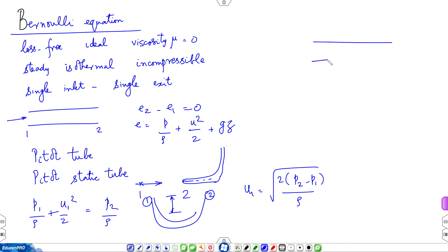Let us say this is a duct, then the pressure is the component of stress that acts normal to the surface. So, you create a small tap and let that pressure act on another surface, that could be a diaphragm or a spring or a liquid column in a manometer. So, you can measure P1 by having